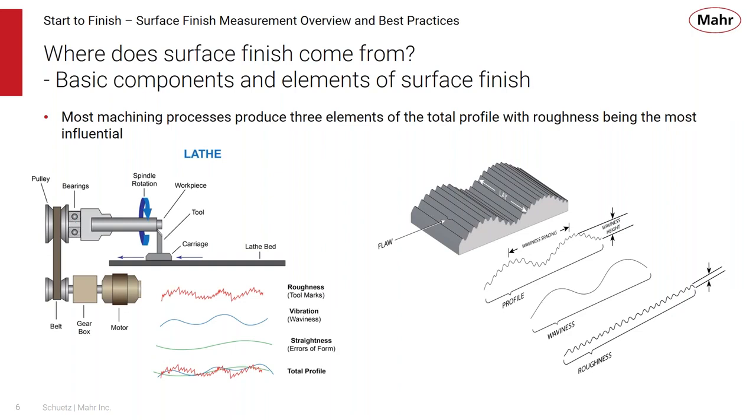And all those really become a fingerprint on the part. So here's the example of the tool marks, the vibrations, which is causing waviness, long-term straightness errors or form errors that can be imprinted on the part. So all those things give us a total profile, and they can be separated out by different types of filters, but roughness is the one that most importantly affects what we're trying to measure in a part, and that's what we're going to talk about mostly today.